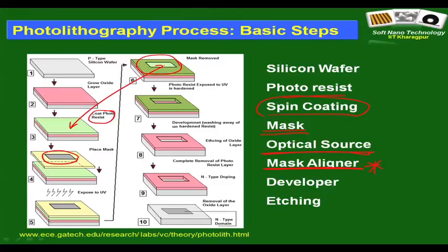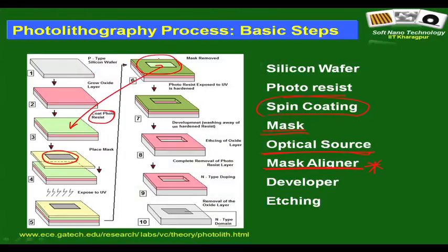What does it mean? It obviously means that only this area was not exposed to the UV light, and therefore the photoresist layer over that area does not undergo any change in property. Without knowing whether it is a positive photoresist or negative photoresist, you cannot comment at this stage whether the areas where the photoresist layer was exposed to UV light have strengthened or weakened, but you can definitely comment that over these areas the property has changed.